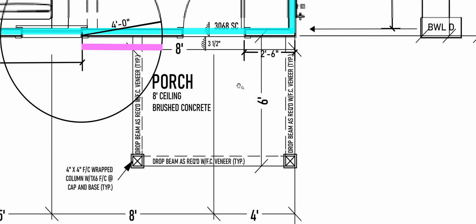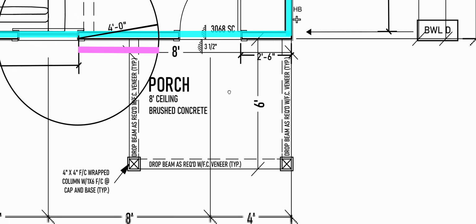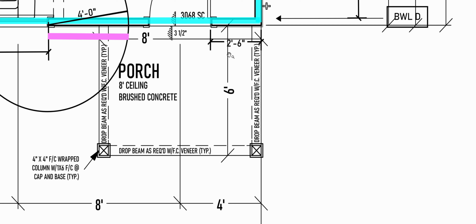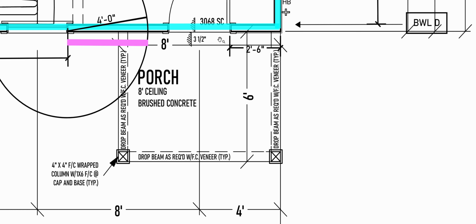Okay, so here's sort of a dilemma. This is a 3 foot wide door. So that means the slab of the door is 3 feet wide, but I need a framed opening 2 inches wider than that. So if I took 4 feet and took off exactly 1.5 feet, then I'd have my 2.5 foot of sheathing panel. But the problem is that I have to lose an extra inch there. So I'm technically too short by an inch.